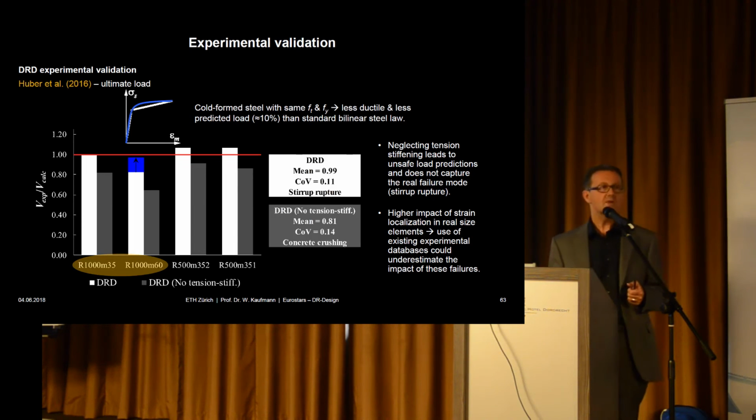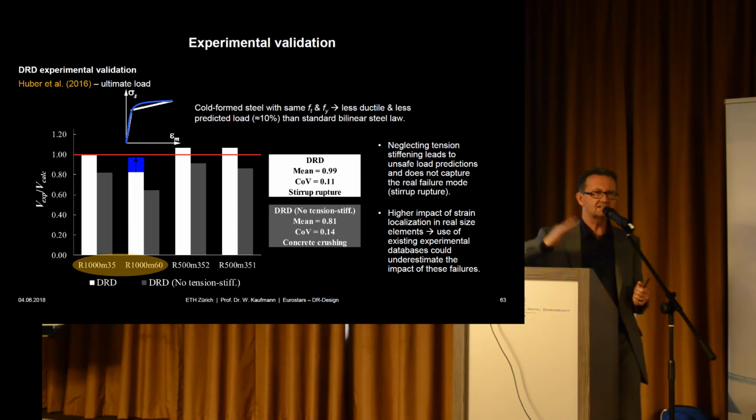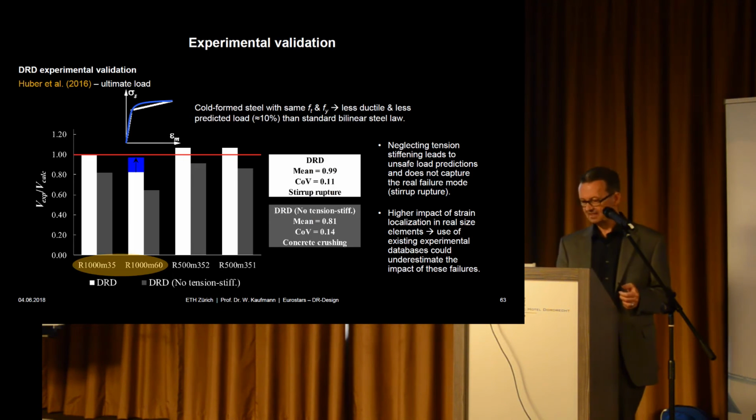It was also made because we have many engineers in Switzerland that use extremely flat inclinations of the stress fields to assess existing bridges. And that's exactly where you get these problems with the stirrup ruptures. And then you have these very thin stirrups with extremely good bond conditions, and they tend to rupture. And I'm a bit afraid that there sometimes we maybe are not on the safe side. That's why we also did these calculations. And Kollegger's tests show that it's really an issue.